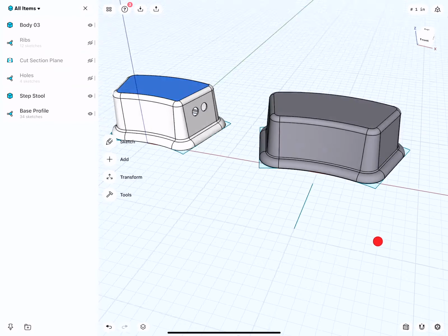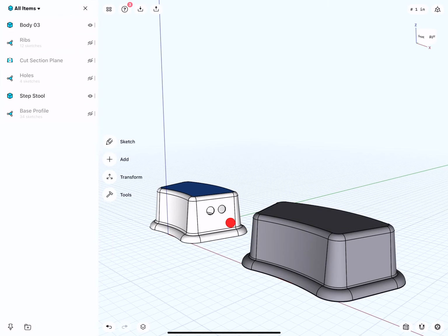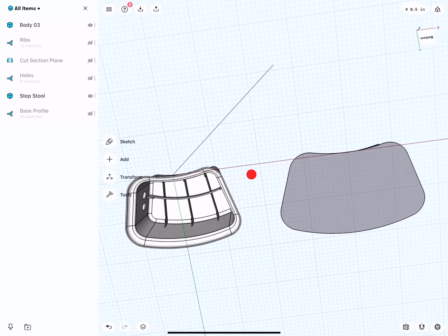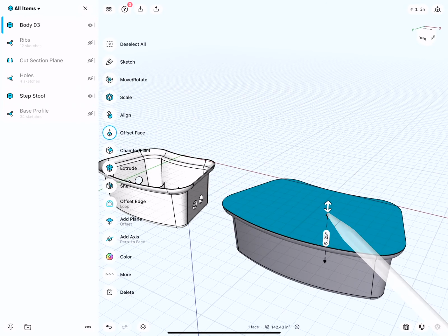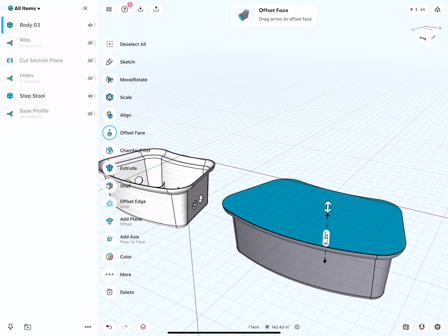The next logical step would be, at this point, we can go ahead and core it out, because now I can cut the holes, and then I can add the construction support inside. So with that face selected, we go to More, and oops, sorry, no, it's already there.